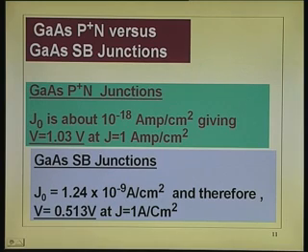That low number makes it very, very small. Ni square is 6 orders of magnitude smaller. That is why it is so low, and when you use V t logarithm of J by J naught for 1 ampere current density, you get about 1 volt.